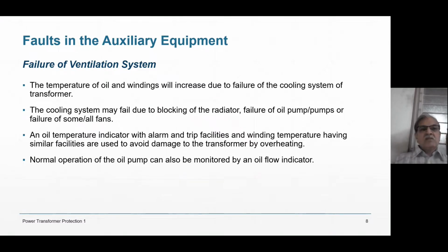So if you want the transformer to deliver its full MVA, then oil pumps should be running, and below the transformer tank, big fans are there. They are continuously running. But if one fan fails, then the cooling will not be sufficient, right?